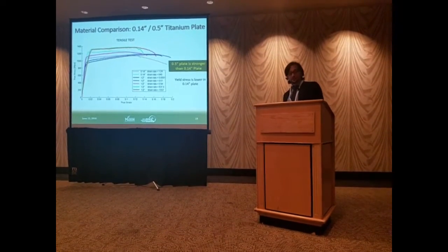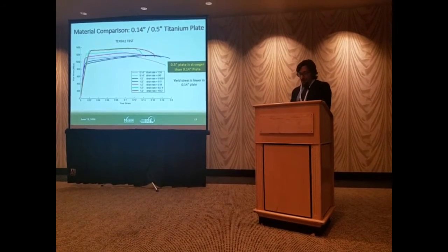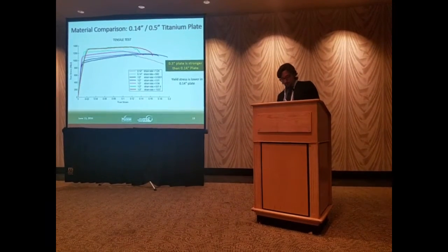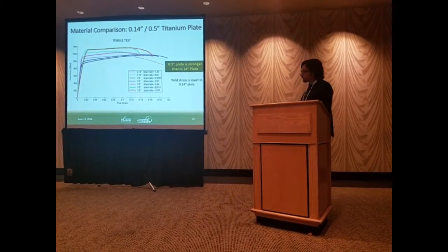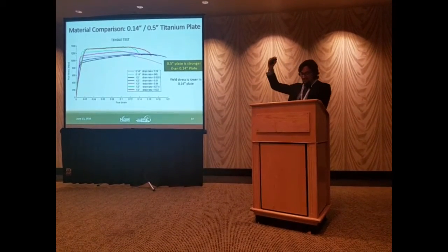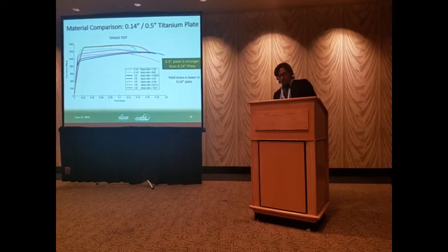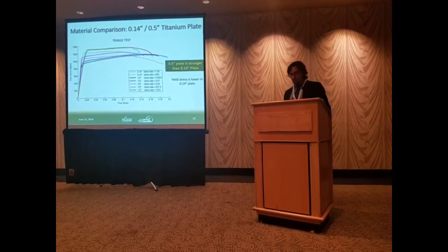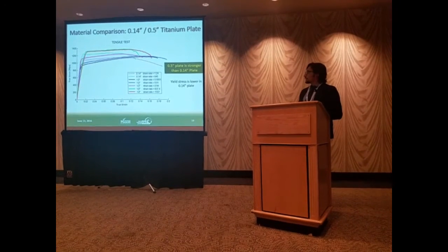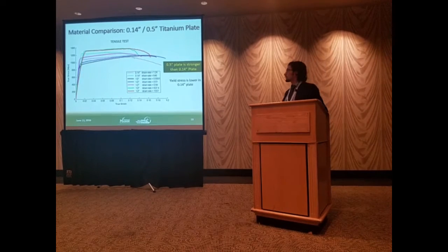But I want to highlight that in all these materials, you have a trend where the higher the temperature is, the later you go to fade. And the higher the strain rate is, the earlier you go to fade. But unfortunately, if you increase the strain rate, you also increase the temperature. So you always have both effects that simultaneously come in and fight each other. Which one is going to be dominant? It's just a lot of tests, is the answer.